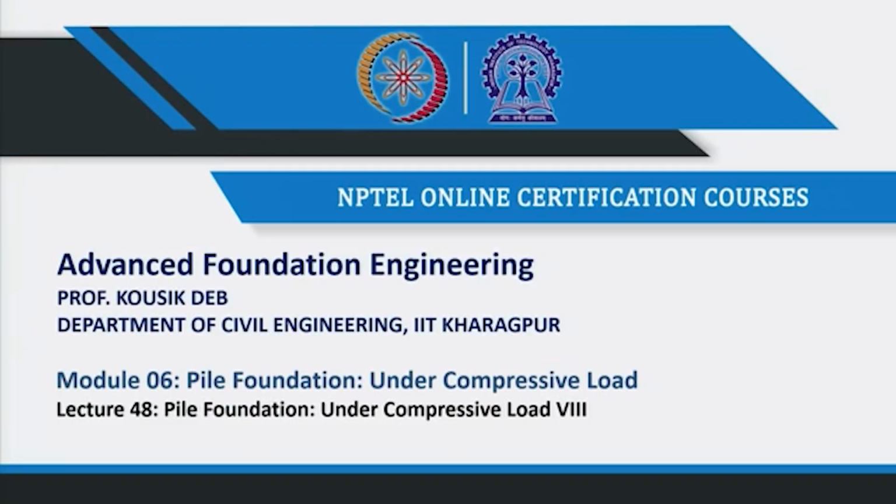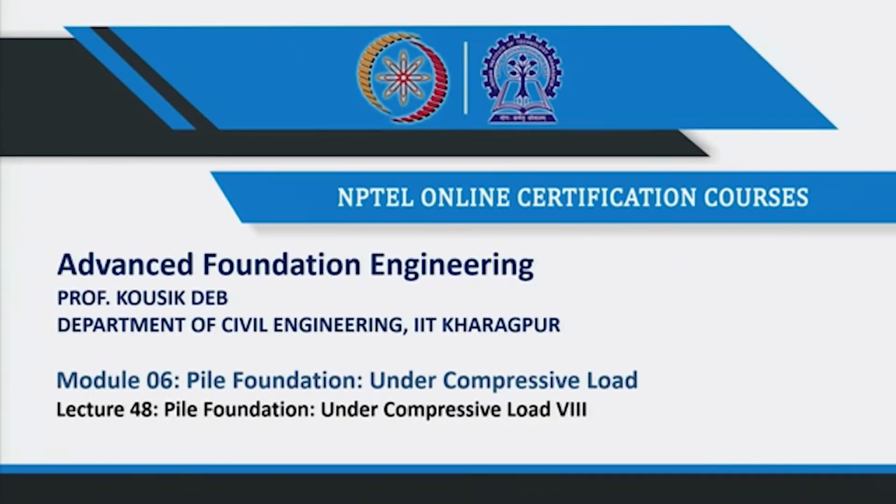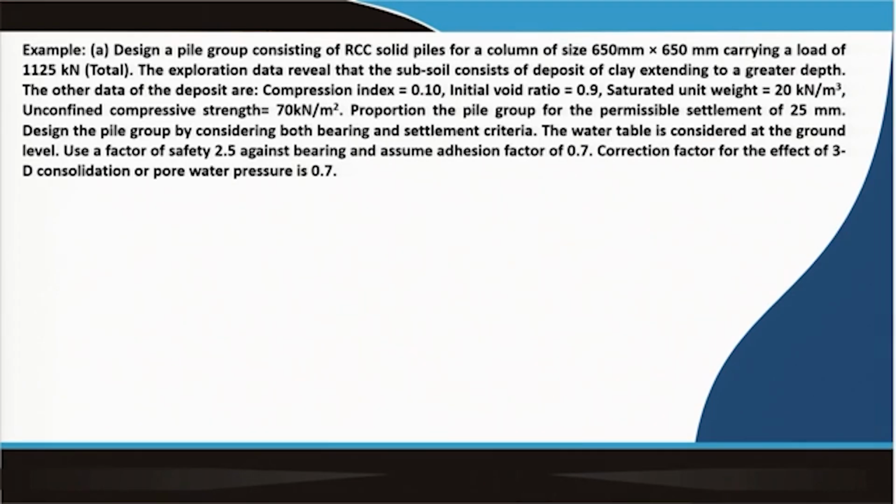In this class I will discuss how we can determine the group load carrying capacity of the pile, and then how we can determine the settlement of a pile group in clay. This is the problem given here: design a pile group consisting of RCC solid piles for a column of size 650 millimeter by 650 millimeter, carrying a load of